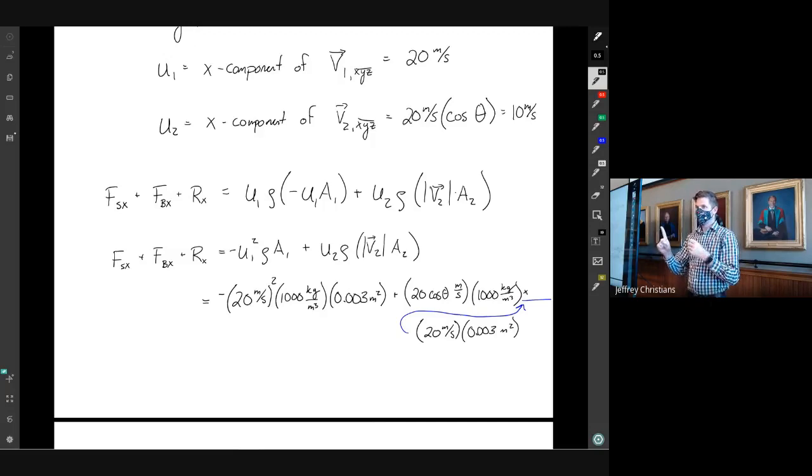And then the y force is, okay, what has to push up on that jet, which started at 0 because it has 0 y component. We have to push up on it to get it to be moving at sine 60 times 20 in the y direction. So our x force is going to be slowing down the jet. Our y force is going to be pushing to speed it up in the y direction. So those are the two components that we end up having.